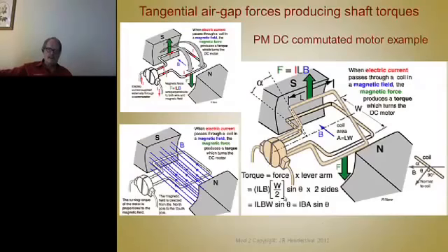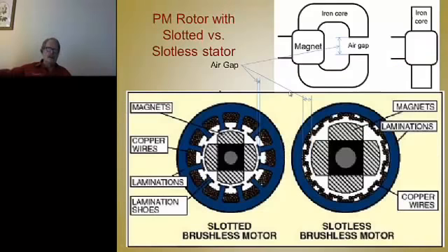It goes from north to south here. So there's a force created on that. The current's the right polarity going through that coil, so there's a force on that wire. But the stator can't rotate, so according to Newton's law, there's a reacting force against the rotor. So it's the rotor that moves, and the field moves with it. So that's why you've got to commutate.